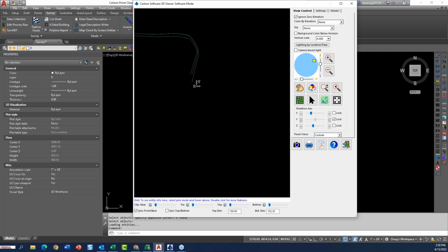So when you create contours, that's going to go up and over just like it's supposed to. With just the straight offset, you're actually going to be making a triangle out of that. So it depends on how important that is, but it's kind of nice to have your surface model reflect what's actually out there. And that's a real quick, easy way to do it.